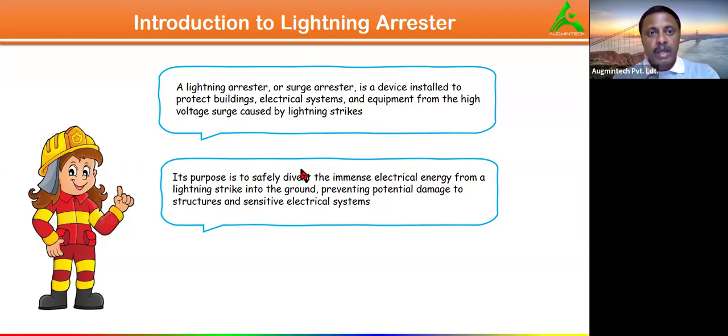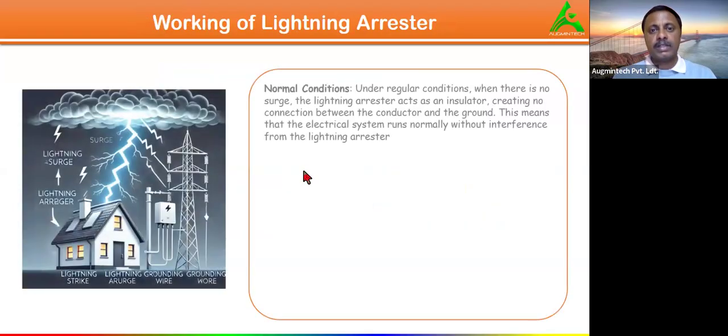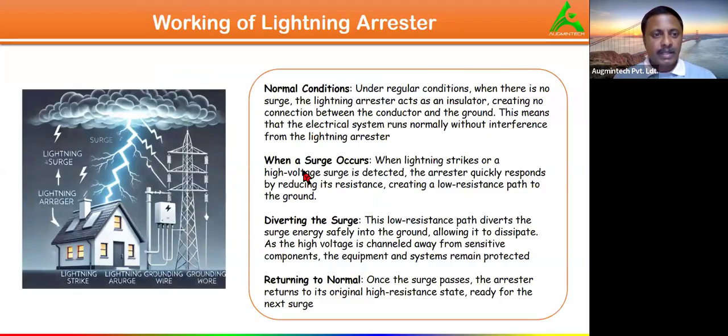Okay. And in the case of data centers, or any components that deal with electronics, because electronics are more sensitive, we have to install surge arresters in their respective DBs. Like if it is a data center, we'll be using a UDB, the usual supplies through UPS, right? So we call it a UPS DB, and inside that UPS DB we need a surge arrestor. Maybe the lightning might be striking the exterior of the building, but it may still affect the interior part also. Since these electronic components are sensitive, we have to install these surge arresters.